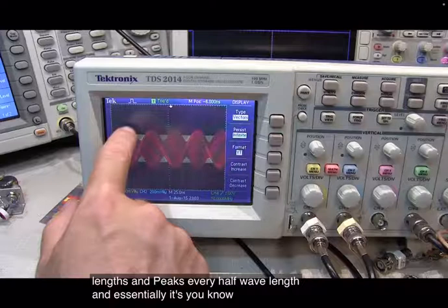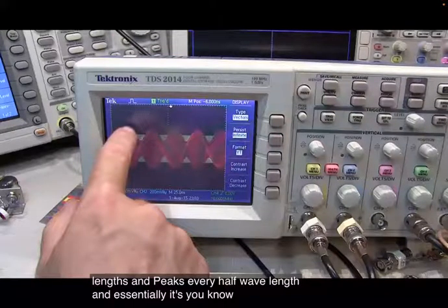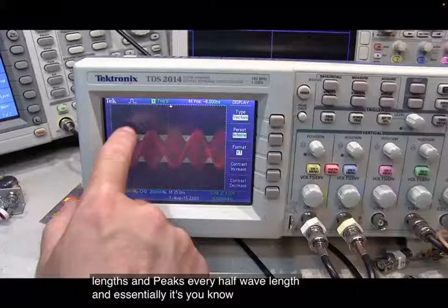The current on the transmission line, same thing. So now you've got the weird situation where, depending on where you measure it, the voltage can change and the current can change from one point to another. Just a little foreshadowing here, what's coming probably Monday. What's impedance? The ratio of voltage to current, right? It's V equals IR. That means, depending on where you look on the transmission line, the impedance changes.